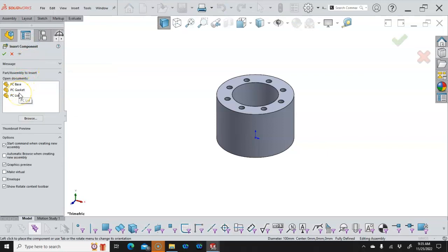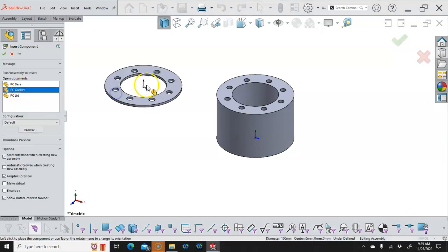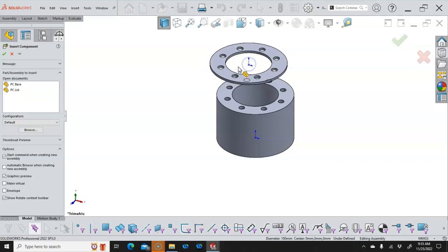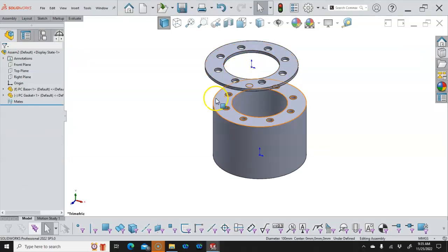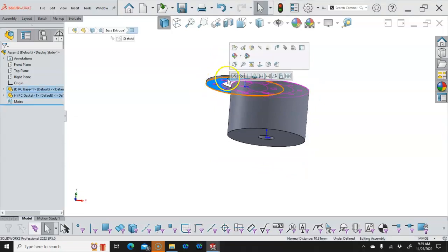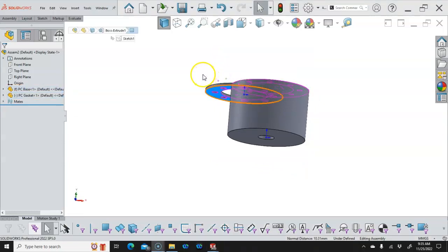All of these parts are open, and memory hasn't been as much of an issue, but I still like to control how many parts I have open, so I'm still probably going to limit that to maybe 6 to 10 at most, depending on how complicated they are. But if I notice any performance drop off, that'll be the first thing I look at, is closing off some of those parts. All right, so we'll do the select, control select, rotating over to see our geometry.